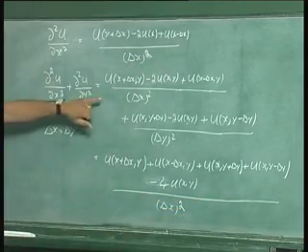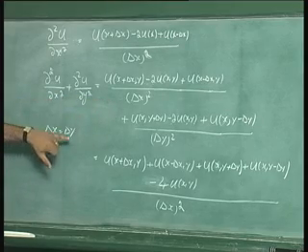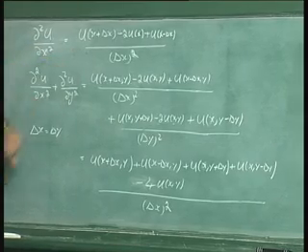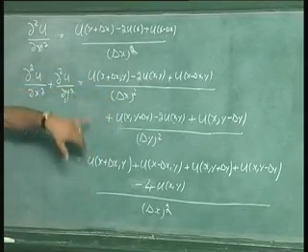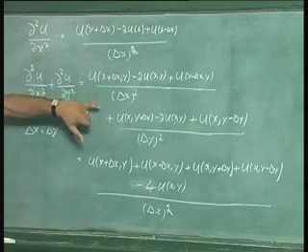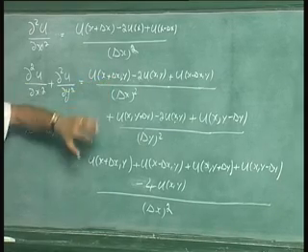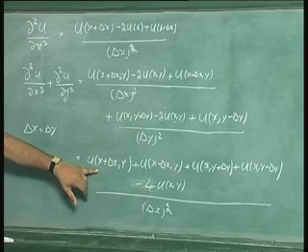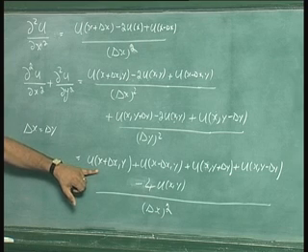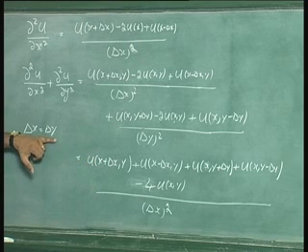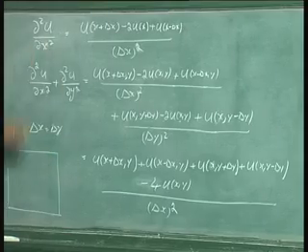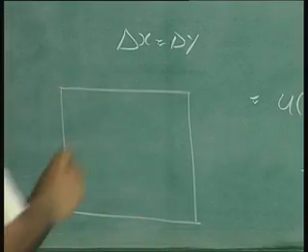Okay, so in this special case where delta x and delta y are the same, we are going to replace all these derivatives by their difference equation. That means we are going to discretize space and write this in a grid, so that x goes up by delta x and y goes up by delta y from point to point. So you take a piece like this, and you want to know, for example, the temperature distribution inside this. Then what we do is